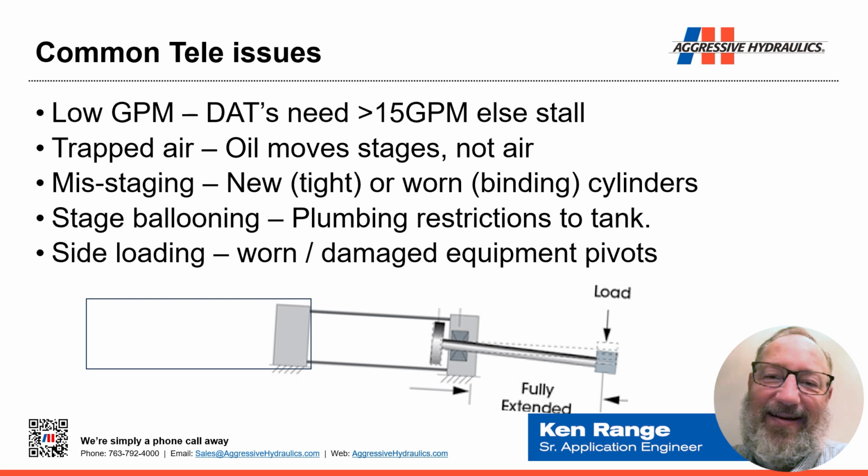Those forces can be hundreds and hundreds and hundreds of pounds when there's only a load applied that's a pound or two because of the multiplication factor of the lever arm. And so side loading can lock up any type of cylinder, whether it be single acting, double acting, rod type, or whatever type. We always have to be sure that there's never a side loading situation with an installation because a cylinder isn't capable of fixing that, geometrical misalignment.